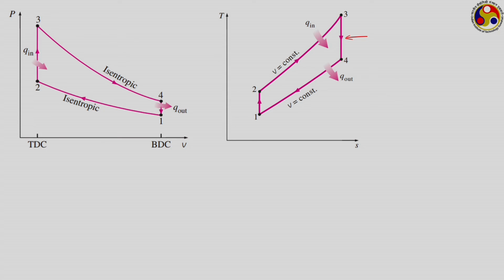So, we have to perform the mathematical analysis of this quickly, something that we did in the previous lecture, but I would like to repeat it, because of the mistake that I made there; I do not want to make it once again. Just as we have done earlier, the amount of heat transfer can be used to get the expression for the efficiency, sometimes called the thermal efficiency or first law efficiency, which is net work output divided by heat input.